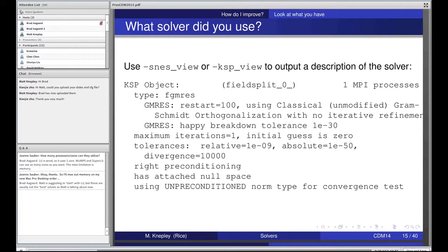And of course, in PyLith, you would say --PETSC.KSP_view. So here it says we have a linear solver. I should use the arrow, I guess. Where's my, I just have to click on it. There we go. So here it says we have a linear solver. Now what's this? This is the prefix. And the prefix allows you to control each part of the solver individually with PyLith options by giving this particular prefix.